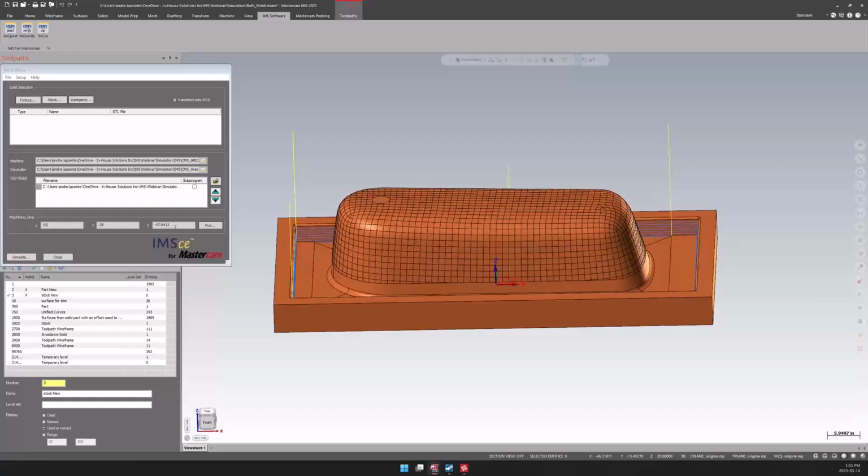In my case, the machine simulation origin is at the machine origin, so I need to set a -X, -Y, and -Z value to position this on my part, on my table. And by the way the simulator has been built, this will give me pretty much the exact values that I'm going to have in my work offset table on the control to be able to run that program without any over travel or anything that I would see in my simulation itself.